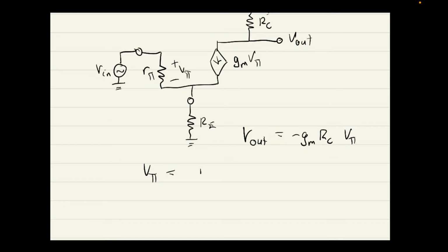It's not capital. Okay, so we end up getting this, but since we're going to take the resistor over from the emitter to the base side, we're going to add a 1 plus beta over here.